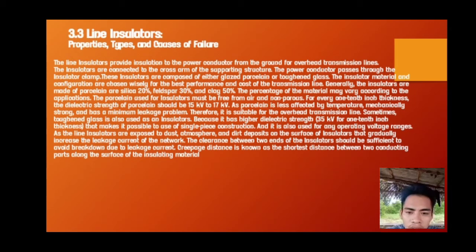For every 1/10-inch thickness, the dielectric strength of porcelain should be 15 kV to 17 kV. As porcelain is less affected by temperature, mechanically strong, and has minimal leakage problems, it is suitable for overhead transmission lines.